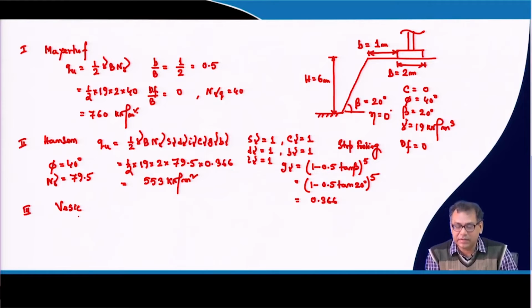Remember that if it is eccentric loading, as per Hansen, whether it is parallel to L or B, all these issues that I have discussed you have to apply here, if your footing is that kind and loading is that kind. Because here I have taken the simplest one, the strip footing, vertical load, no horizontal load.